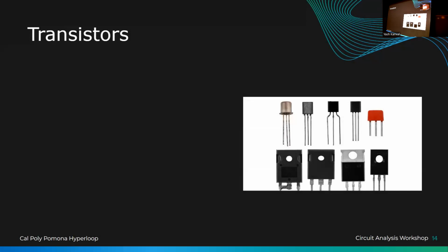And that's the danger of electronics. Fail safes are very important, and a diode is one of them. If you put a diode there, even if the user decides to flip the wires, the current will not go in the reverse direction of the diode. It'll be blocked from going the wrong way and destroying stuff in the circuit.